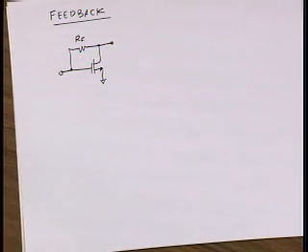Potentially, depending on how we design it, right? Well, let me give you a hint. What if I make RF small? Or alternatively, what if I go to really high frequencies? Anybody have an idea? Yes? Is that because the assumption of unilateralism breaks with this? Yeah, there's going to be quite a bit of feed forward, right?